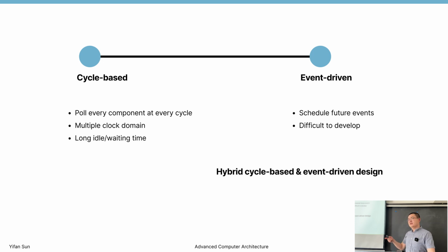But because the leading developer is no longer working on that project, it is basically not maintained. It takes a hybrid simulation method for the core. They think, oh, it's very common for the core to still need to tick, tick, tick, tick, right? But for the memory side, it's more like every action takes a longer time. So the core part uses cycle-based simulation. The memory side uses event-driven simulation.